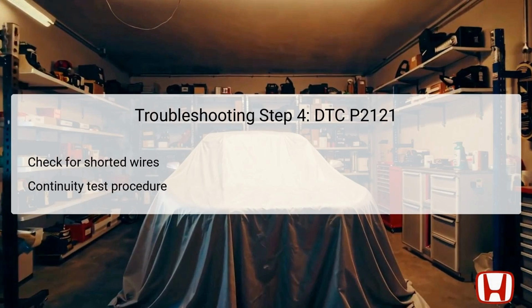In the fourth troubleshooting step, a focus on the potential for shorted wires is essential. After turning the vehicle off and verifying the HDS is in SCS short mode for more than 1 minute, the technician disconnects the PCM connector A51P. Conducting a continuity test between specified points allows for precise determination of any short circuits in the wiring.